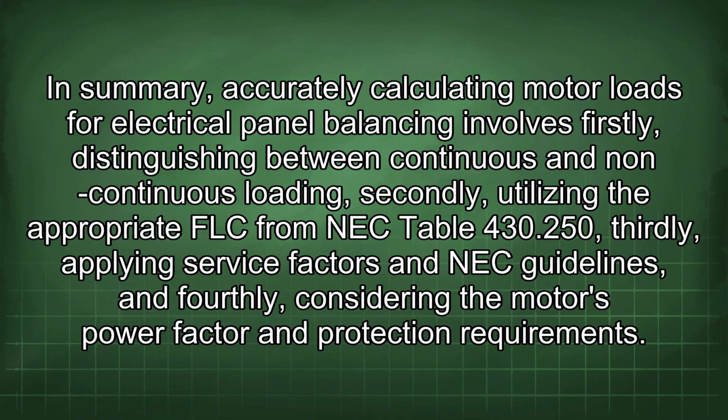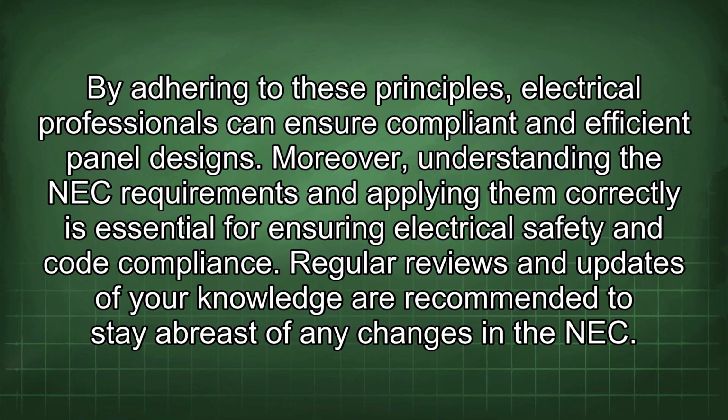In summary, accurately calculating motor loads for electrical panel balancing involves firstly, distinguishing between continuous and non-continuous loading, secondly, utilizing the appropriate FLC from NEC Table 430.250, thirdly, applying service factors and NEC guidelines, and fourthly, considering the motor's power factor and protection requirements. By adhering to these principles, electrical professionals can ensure compliant and efficient panel designs.